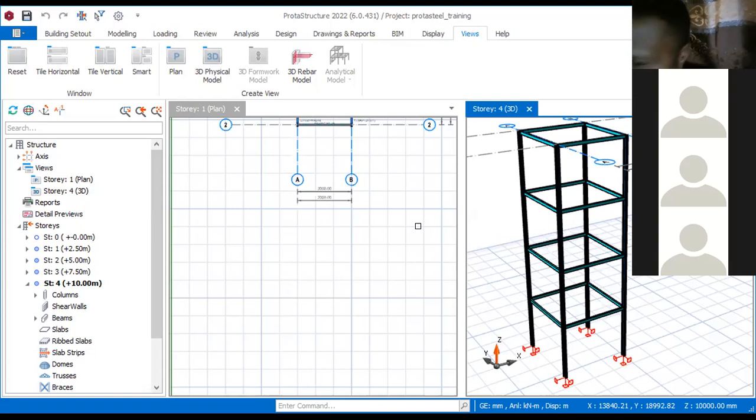I think because of the bracing, we cannot just run twice the height. We need to brace the horizontal member at different intervals. I think that's why we're having 2.5, 2.5, and 2.5. For it to just run from the base 12 meter or 10 meter up is not too safe, because of wind load and the load that is going to be on top. Yes, you are right.